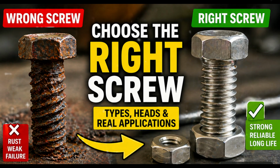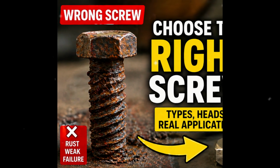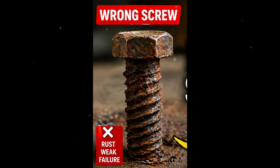Now, look at this image very carefully. On the left side, you can clearly see corrosion, rust, surface damage. Now, as an engineer, what does this indicate? Corrosion has reduced the effective diameter, which directly reduces load carrying capacity. Surface pitting creates stress concentration points, and under cyclic loading, fatigue failure becomes faster. So, this screw is already in a failed condition even before complete breakage.